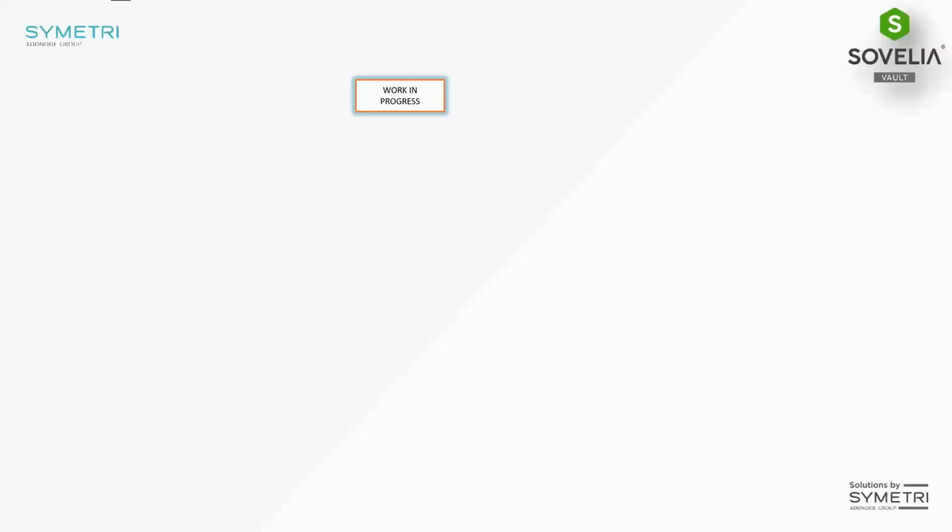Just briefly, let's talk about a typical workflow, just so it makes it a little easier to understand some of the actions that will occur as we go through a workflow. So this is just an example workflow. Typically we might start with our drawing. We might start in the work in progress stage. We may need to submit just to a check. So we just have a check state set up in the Vault. Not everybody uses the check state. Some people go straight to the review stage, but check state is available in Autodesk Vault also. And when that check state occurs, we might require something like an email notification. And this is something we can do with Sovelia Vault. We can trigger emails that go to someone to come in and check this particular file.